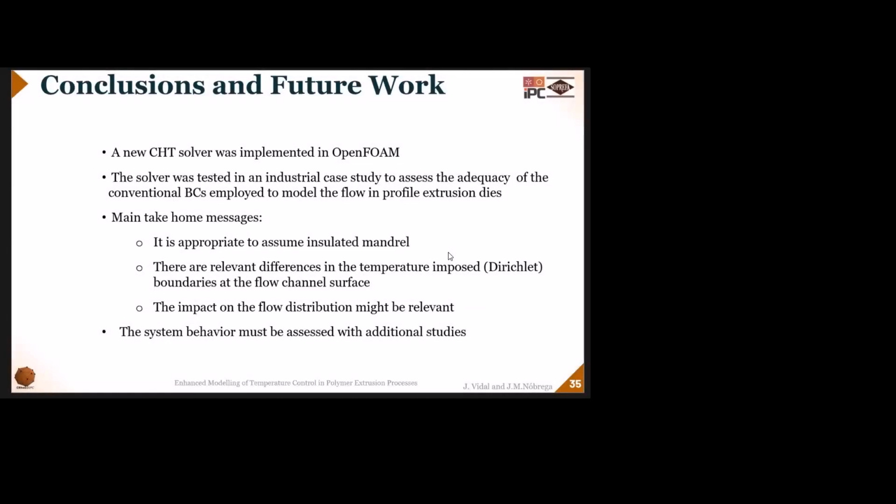So, conclusions. We were able to develop a new CHT solver in OpenFOAM. The solver was tested with an industrial case. The message to take home: it's appropriate to assume that the mandrel is insulated. We can model it as insulated.